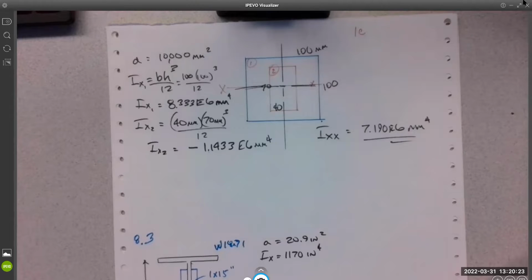And the reason we're doing that is because everything has a factor of safety on it. So our accuracy is important, but we're also going to be factors of safety below any limits. So if we have a limit of 10, we're not going to ever get to like 10 or 9.96, right? We're going to be factors of safety below a limit of 10. We're going to be down around 7, 6, or 5.